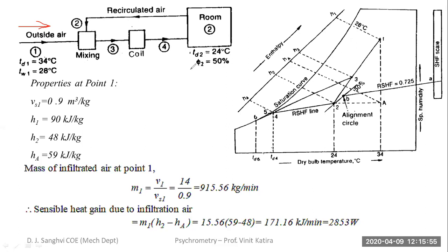Yes, sir. Okay. So next you will open your psychrometric charts, and you will plot these 2 points. That is the point number one, that is the outside condition, and point number two, that is the room condition. Okay, you will plot these 2 points.